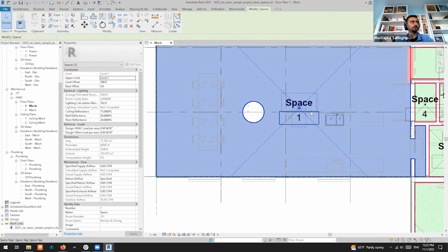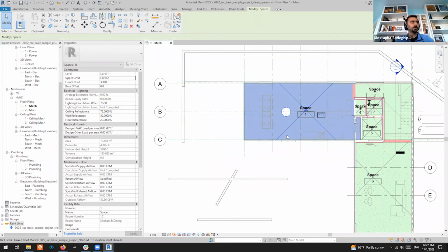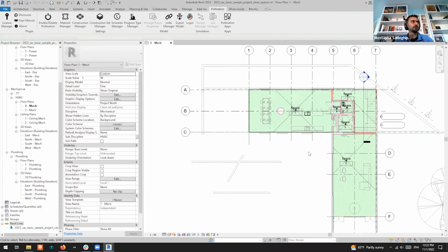So if we can have something and say, hey, remove any hole or space that's smaller than something. If you bring it to Rhino, we added a new command, or the command was there, we improved it: you can do untrim, and by untrim you can quickly click on them and they will be gone.